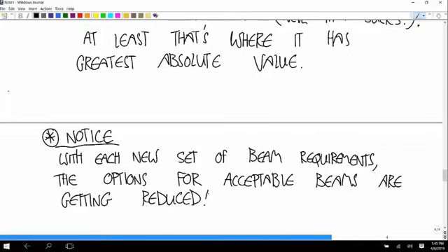So now if you have an internal loads problem, where you solve the internal loads and you get bending moments and shear force at the points you're interested in, now you can only calculate the stresses if the thing is a rectangle, or if the thing is circular, but then you can only do it at the neutral axis.